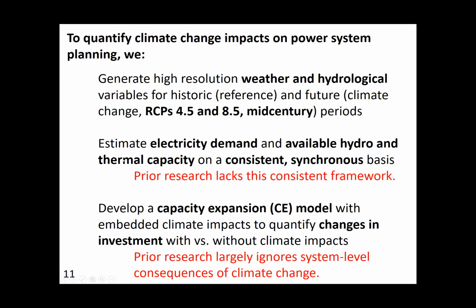It minimizes costs. And we're going to take that capacity expansion model and embed all these climate impacts into it so that we can run the capacity expansion model with and without climate impacts to understand how our investment decisions change. And so the red text here is kind of underscoring our main contributions. One, we want a consistent framework for these different hourly changes. And two, most of the literature is just on those individual areas, temperature to demand, not thinking across a system. And so our main contribution here, I would say, is really looking at planning as a system under climate change.